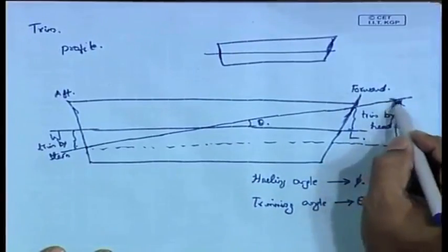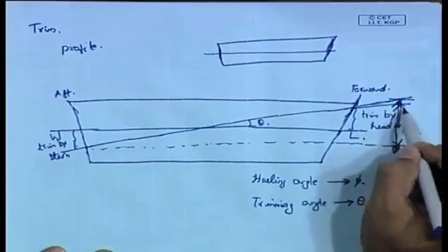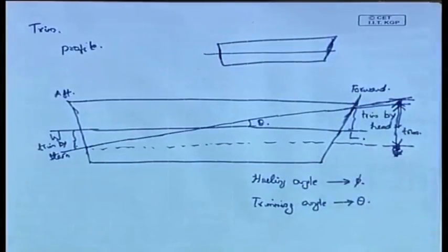To prevent ambiguity in our course, we will define the total distance between the forward topmost part and the aft bottommost part as the trim. This is the distance through which the ship has totally tilted. Okay. So, we now have a ship like this.